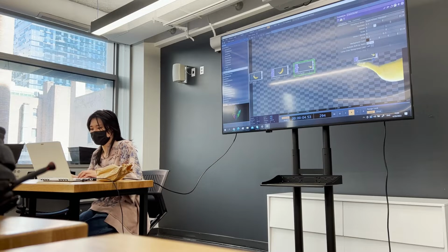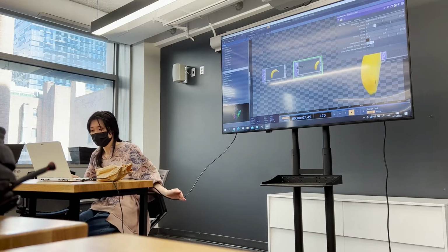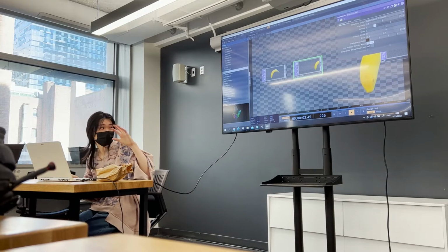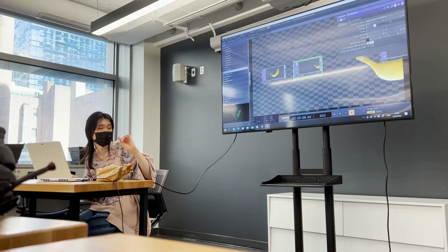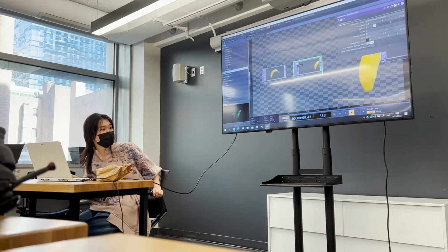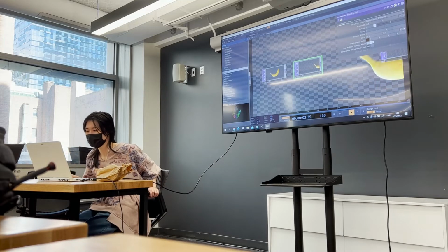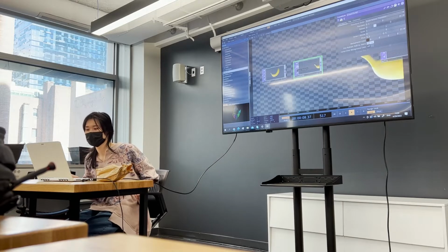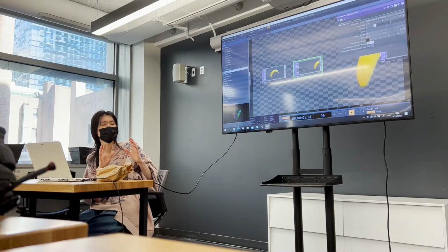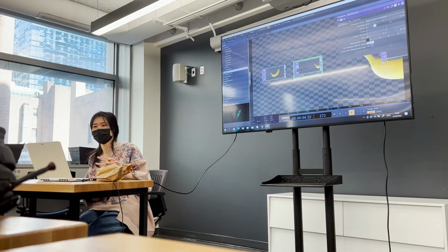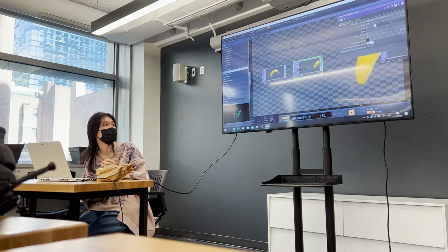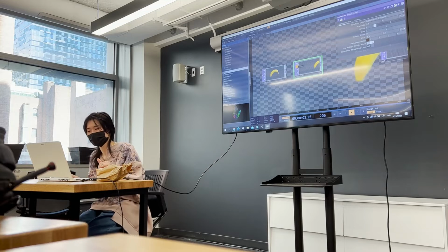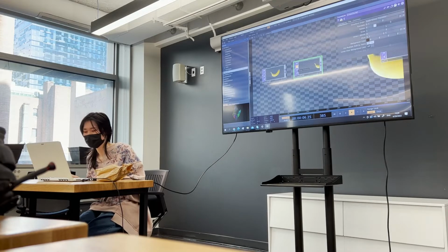Cool. Here's another thing: on the right side of the node, there are four buttons. The first one's the viewer toggle, to turn the viewer on and off, because turning it on, especially when you have a lot of stuff, can take a lot of your processing power away. So when you don't need them, you can just undisplay them. This one's clone immune, which means that there is a component called replicator, which essentially can replicate the nodes, but it also takes more processing power. If you click clone immune, it's going to go very slightly faster, but also be immune to cloning, which we're not going to get into today.